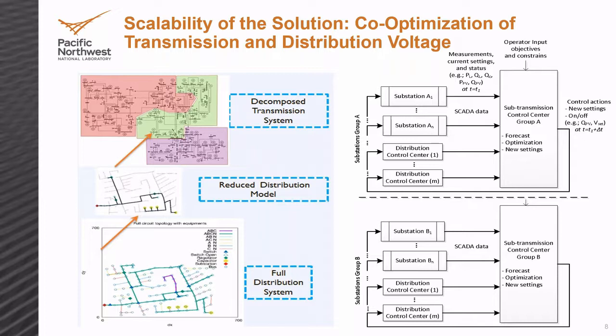So in terms of computational needs, the burden to decouple the interdependency was already taken on by the subtransmission optimization. Now each substation can optimize its own volt-var resources in parallel. So that should happen in a reasonable time for real-time application.